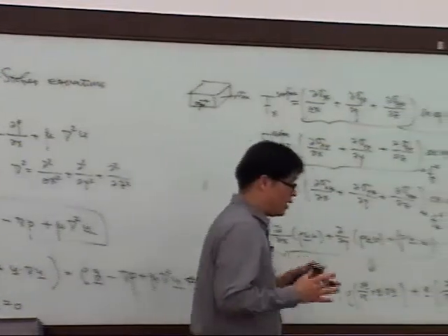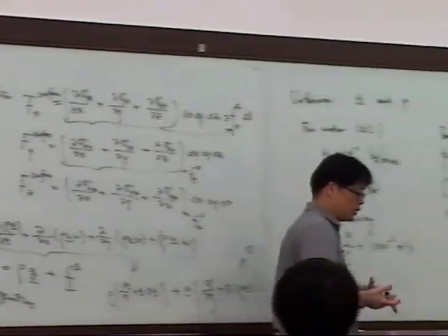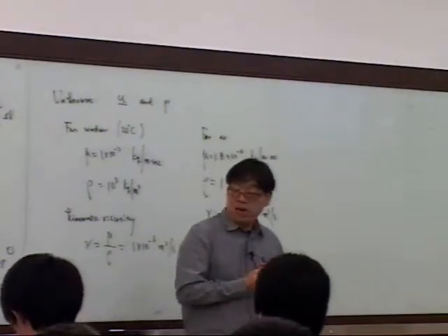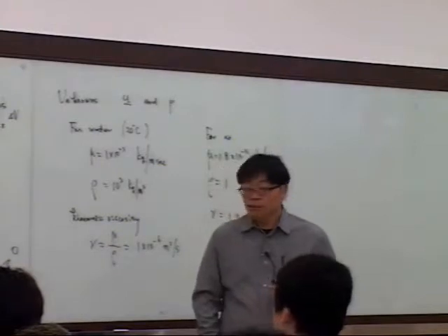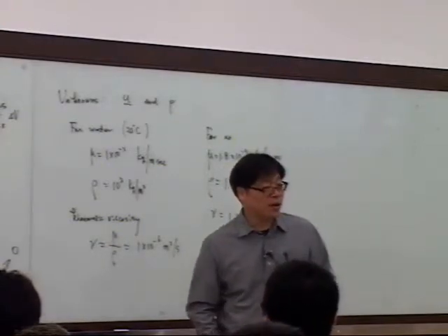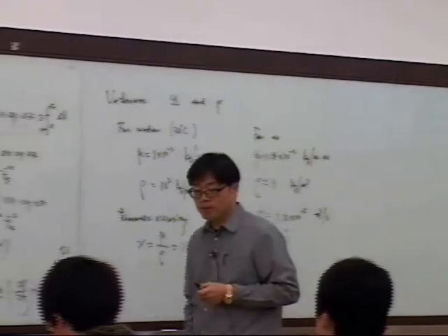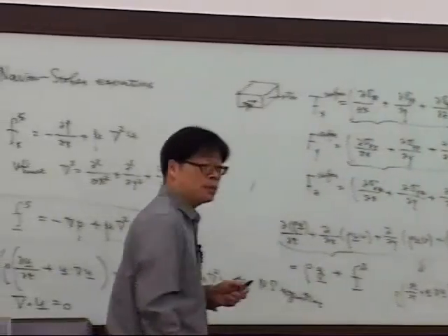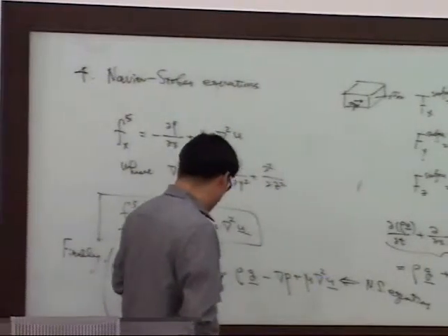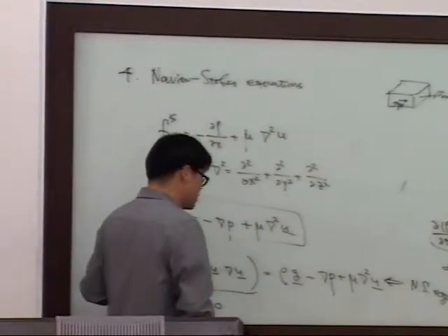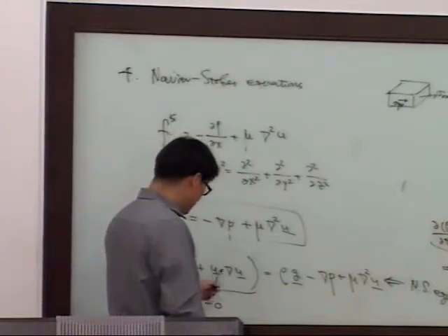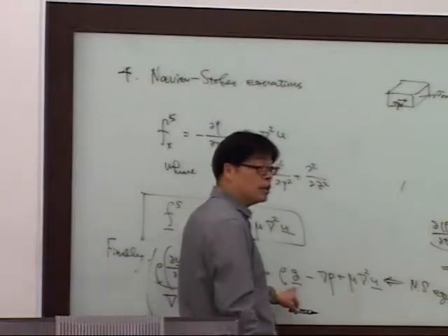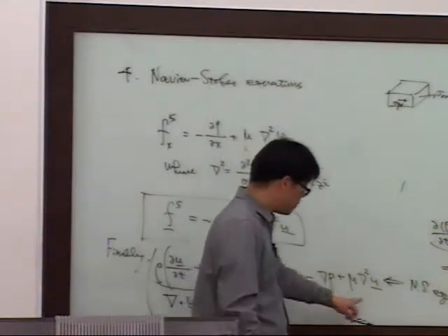So far we have derived the governing equations, the Navier-Stokes equations and the continuity equation. If you don't follow all the details, that's okay, but I hope you look at your notes and go through them at least one time. The important thing is this is basically mass times acceleration. So the rate of change of linear momentum is balanced by the body force and the surface force.